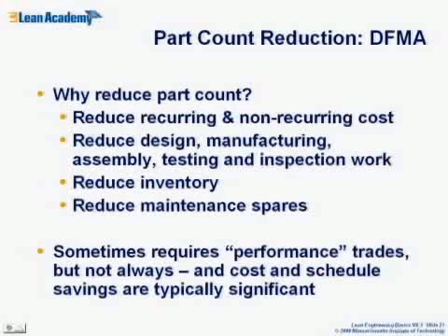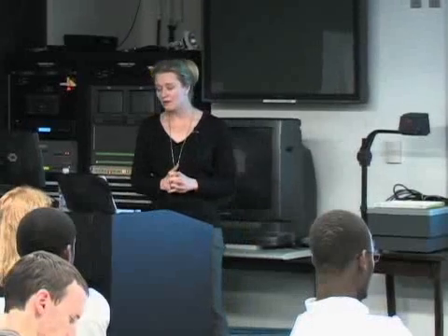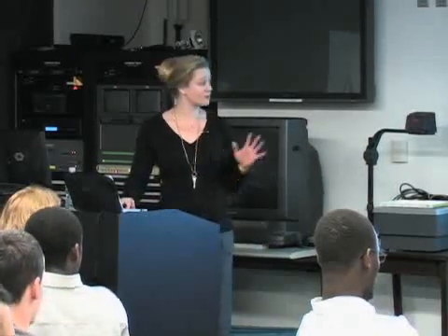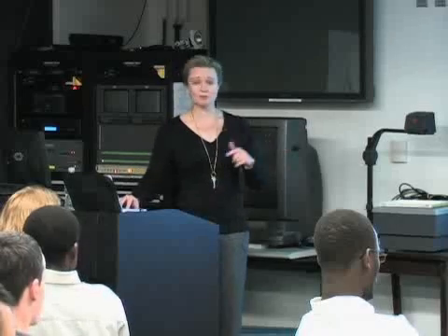They were excellent discussions, and there were some others that we brought up that aren't quite on this list. It's important to keep in mind, though, that sometimes, but not all the time, reducing your part count requires some performance trades. Cost and schedule savings may be big, but you may be trading off a little bit of performance. And if your customer's okay with that, then everybody wins in the end. One particular aspect in aerospace systems is, of course, mass. Sometimes going to common parts and fewer parts can increase mass, which may dictate a performance ding to the system. But like I said, not always, and I'll show you an example later on that demonstrates that clearly.